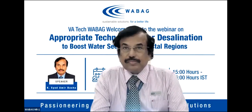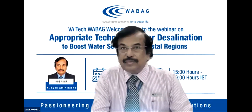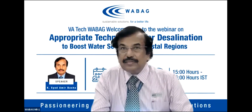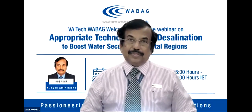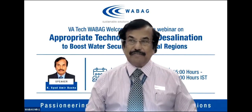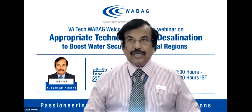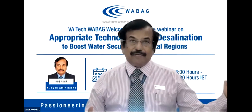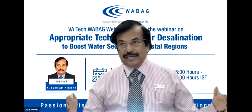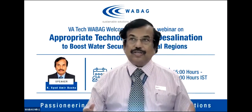The next question is from Mr. Sushil Kumar. In fact, there are 2 questions. Number one, what is the overall efficiency of the entire system in terms of output versus intake water? Generally, if 100 liters of water is taken, in the Nemmeli plant we are converting up to 40%. So the overall recovery rate, from the permeate, that is our potable water produced, to the water that is taken from the sea, is 40%.